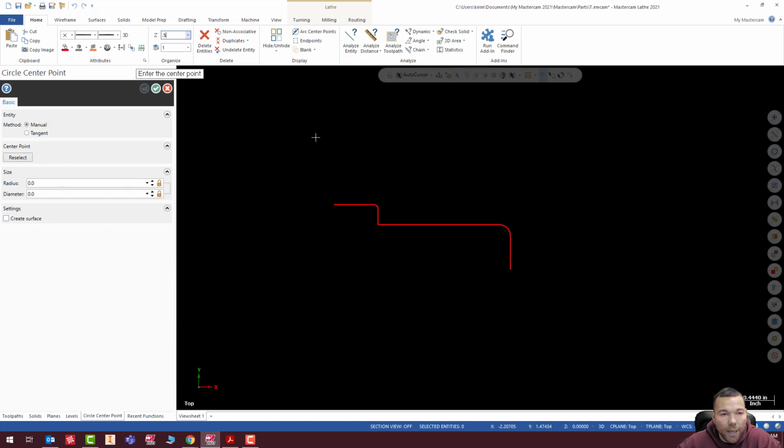Okay, so now I can put in my points. So I'll go to my space bar. Oops, I'm going to get my auto cursor, here we go. All right, so I'm going to put my points in, and that of course is going to be 0, comma, negative 0.25, enter.